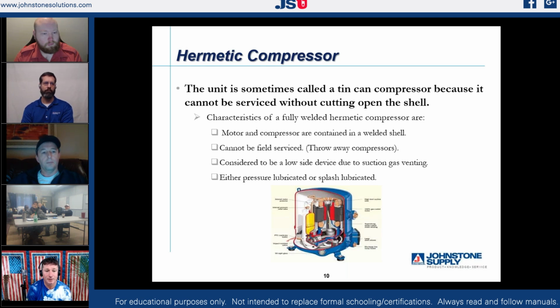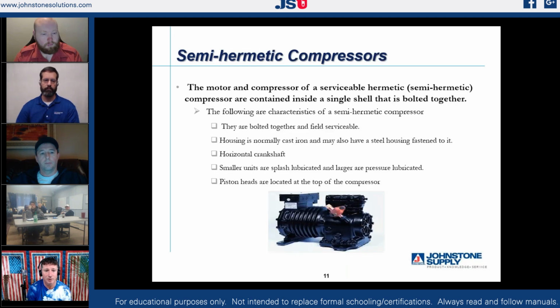Yeah, absolutely. And when we talk about that straight scroll, it'll help you see where we have positive and negative pressure in that pump at all times. And so, yeah, the pump itself, that's when we start talking about compression ratio. It really is a lot to do with the efficiency of our pump.